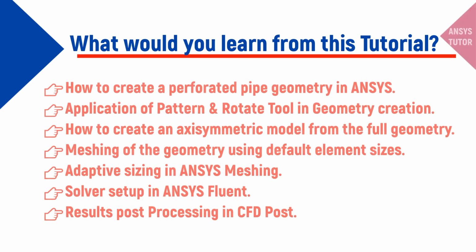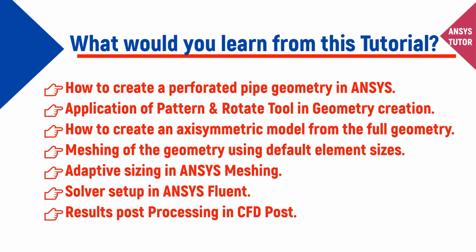From this tutorial, you would be able to learn how to create a perforated pipe geometry in ANSYS. Application of pattern and rotate tool in geometry creation. How to create an axisymmetric model from the full geometry. Meshing of the geometry using default element sizes. Adaptive sizing in ANSYS Meshing. Solver setup in ANSYS Fluent. Results post-processing in CFD Post processing.